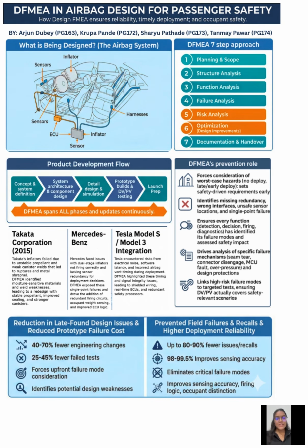Hello everyone. Today we will be explaining a very important product safety tool used in engineering, that is FMEA, and more specifically DFMEA. So what exactly is FMEA? Well, it stands for Failure Modes and Effects Analysis, which is a structured method used to identify potential failures, evaluate the impact of those failures, and prevent those failures before they even reach the customer. In simple words, FMEA is: what could possibly go wrong and how can we avoid it.